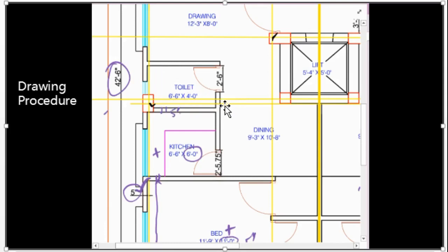To get this yellow line, this center line, we need to add 2.5 inch, because this is 15 inch, half of that will be 7.5 inch, and if we deduct 5 inch from that we'll get 2.5 inch. So adding 2.5 inch more with this 5 inch we'll get this yellow line. That's how you will get this line, and not that line, obviously this line.